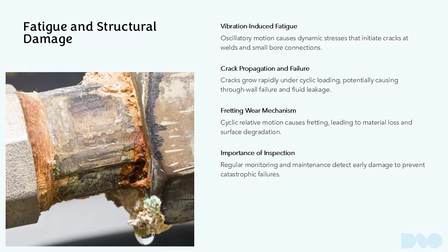Fatigue and structural damage, operational and safety implications. Vibration-induced fatigue is a critical integrity threat in process piping systems. Dynamic stresses generated by oscillatory motion can initiate and propagate cracks at stress concentration points, such as weld toes and small-bore connections. Once a crack forms, it can grow rapidly under cyclic loading, eventually leading to through-wall failure and fluid leakage. In severe cases, catastrophic rupture may occur, posing significant safety and environmental hazards.